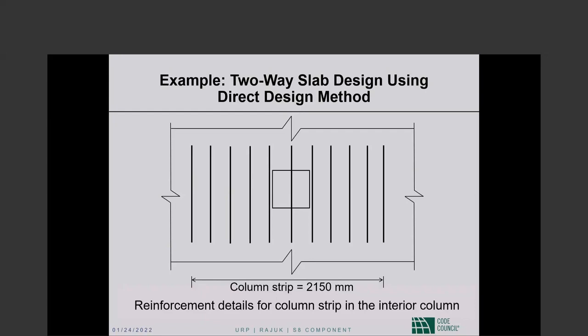Moving on. In our country's slab design practice, we currently practice crank slab rebar. What rebar? Crank slab rebar. I don't know what that is. That is, the main reinforcement is bent from bottom to top. Oh, in the slab.